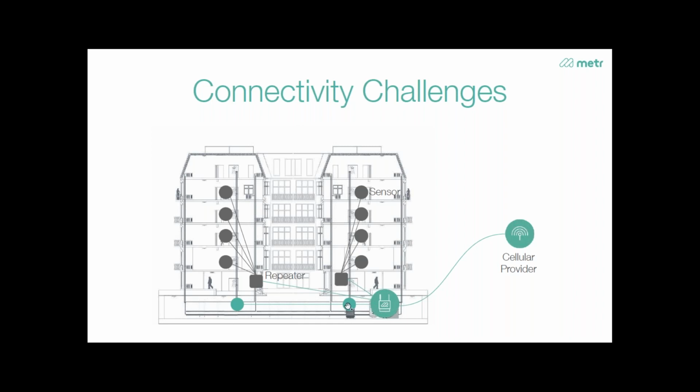What you can see here in color are the sensors that we install, and those are installed by us, which is why they have a different color. But we also read out existing infrastructure, because most buildings already have heat cost allocators or water meters installed. You might have them in your apartment, for example, right? All those devices are continuously sending data, and we either access them directly or go through a repeater. So we read their data and also read the sensors that we install ourselves.